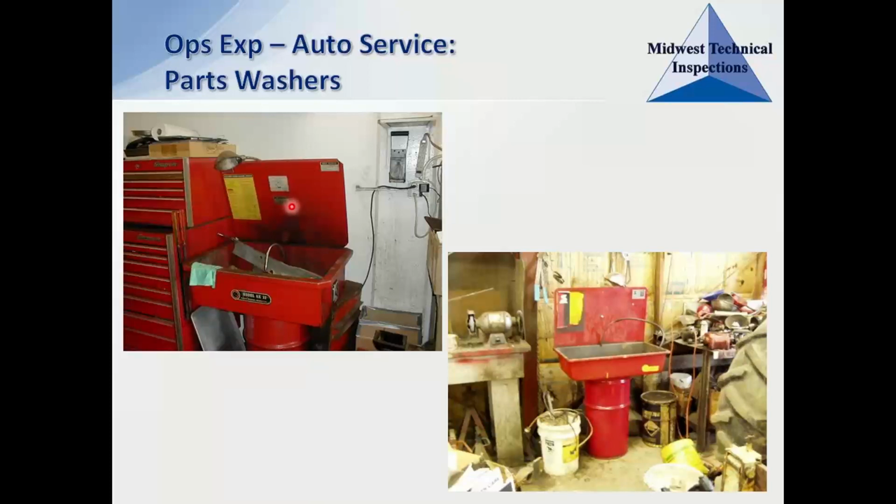And on the back side, there's something called a fusible link. This is basically just a little soft piece of metal that's holding this door in the open position. Now, if there's a fire, that little soft piece of metal should melt quickly, and then it should release this door shut onto the tank here. So it hopefully contains and suffocates that fire so that it doesn't spread to the areas around it.